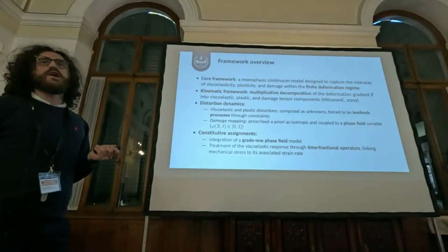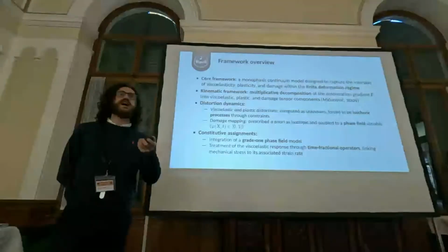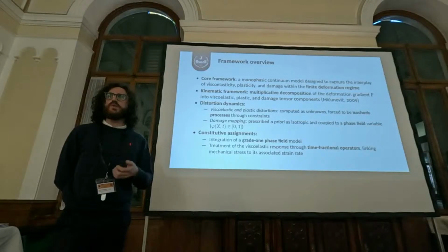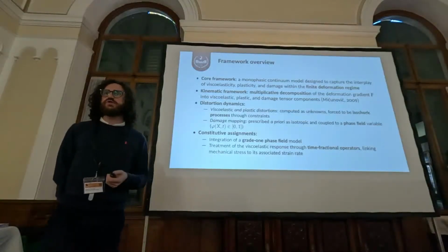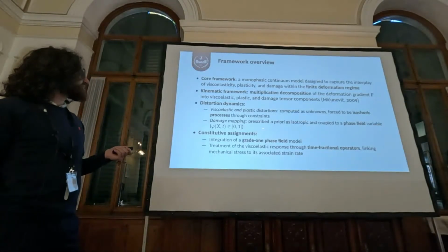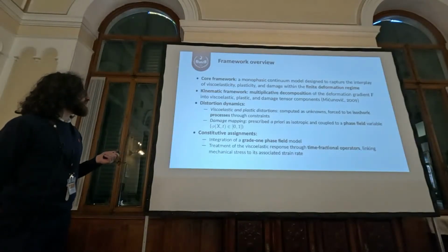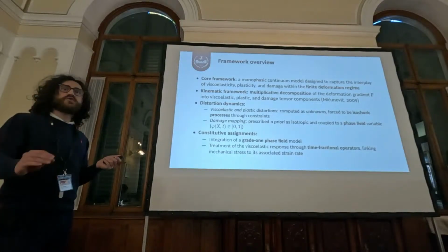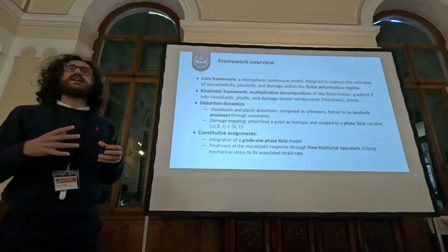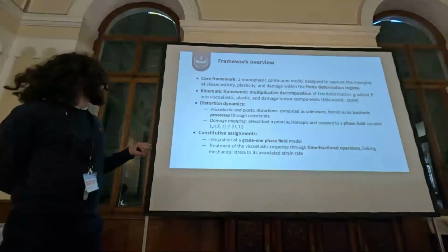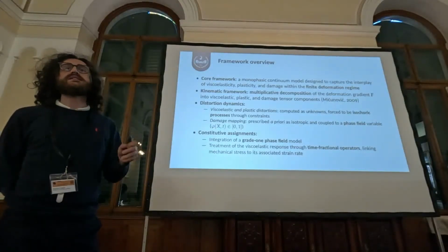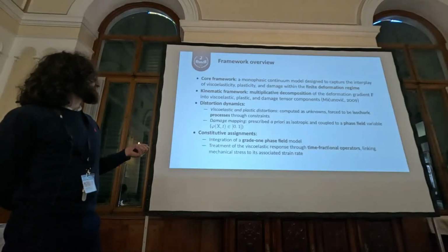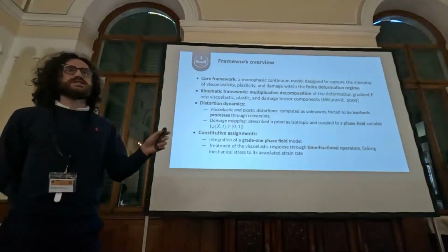The phase field is one of the most versatile and well-known techniques to deal with damage processes in continuum media. It is basically a scalar variable that can span between 0 and 1 and describes punctually in our domain the damage state of our material. When phi is equal to 0, the material is completely pristine, so we don't have damage at all. And when phi is equal to 1, the material is fully damaged.